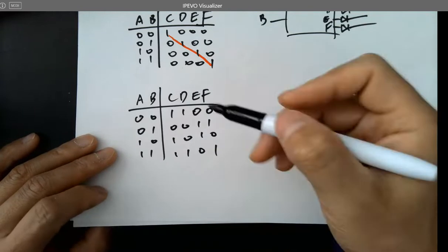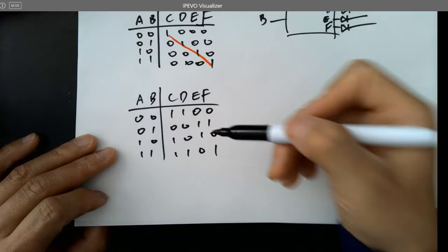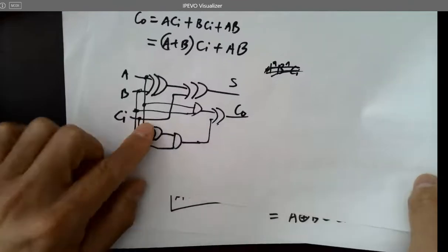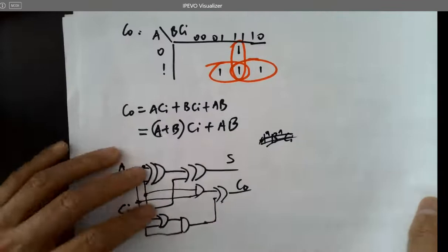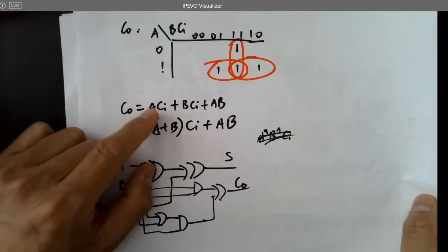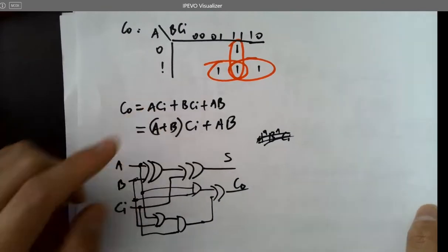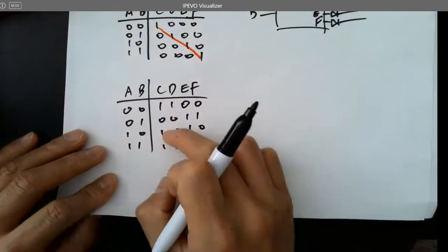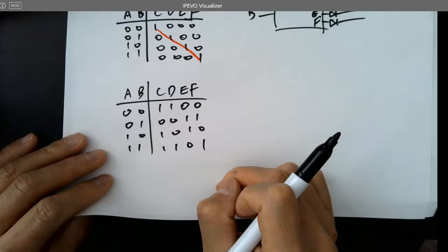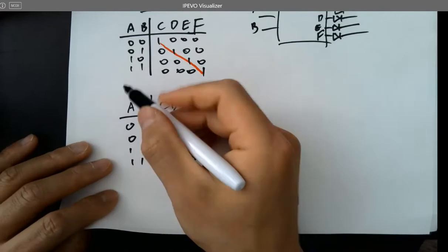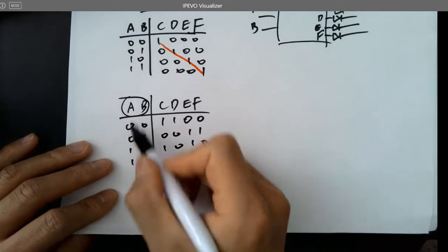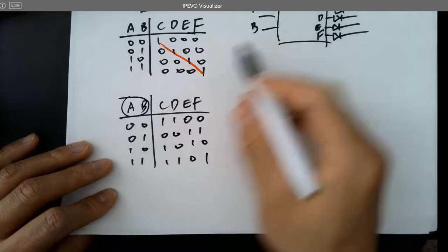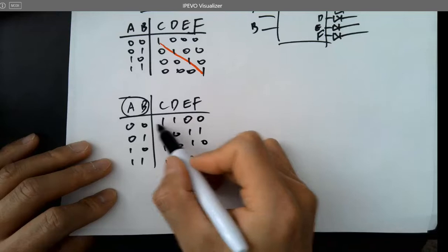But when you are designing this in Verilog, do I need to draw the circuit? Do I need to get to here? No, this will be good enough. Just code it up, and the synthesizer is going to do the job for you. Is this a decoder? Yes, it's decoding. You get a code as an input for the digital block, and it outputs a pattern for you.